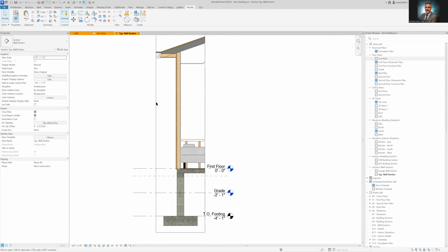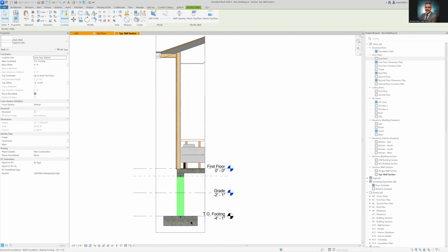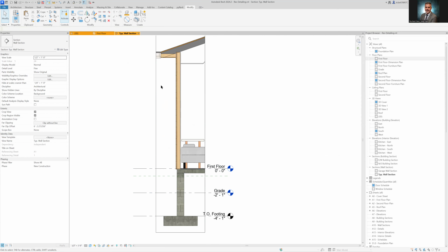All right. So usually when we start annotating these kinds of things and we want to make this look correct, and make this look like concrete with its pattern, I know we usually don't show it in color. So down here in the view control bar, we can go to the hidden line view. I would suggest setting it to the fine level of detail, at least medium, because that way you can get the layers within the walls showing up. So usually most people want to dress up the space with things like the concrete or the different CMU blocks and the insulation, right?